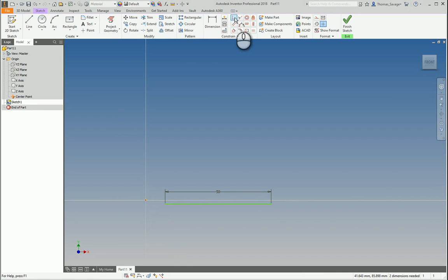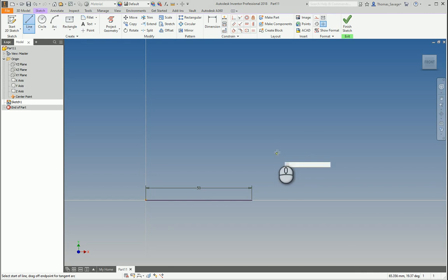So now I will use a coincident, pick that point and place it onto that point. As we see, the little orange square means a coincident, which will bring the F8 up and we select it. And this box with a plane above it, that's the projected geometry, showing that it's projected that shape, which is the square, through to the plane that we're sketching on. Right, so a perpendicular